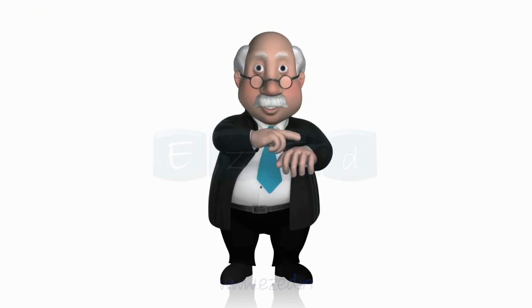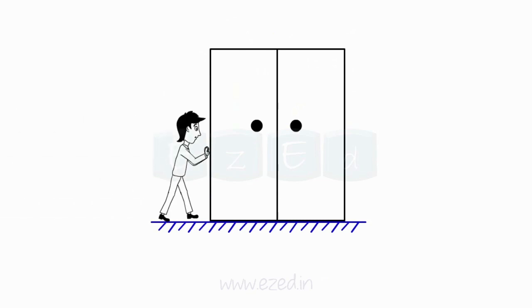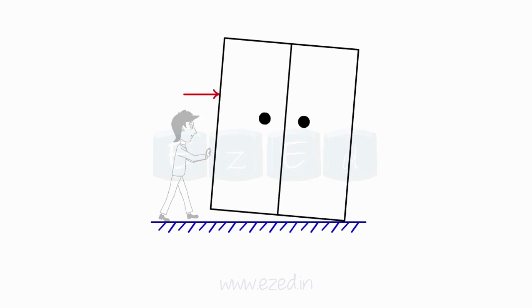Hey, it's time to concentrate now. Tipping is a very important concept that we have seen one or more times in our life. Consider an empty cupboard. If a person tries to push the cupboard ahead, it is easier for him to apply a force at a lower position in comparison to a higher position. If he applies force at a higher position, the cupboard may tip, that is, it may tilt over instead of sliding ahead. This phenomenon of the tilting of the cupboard is called tipping.